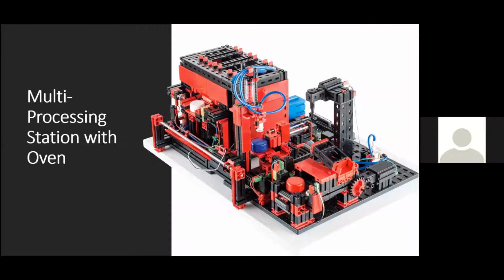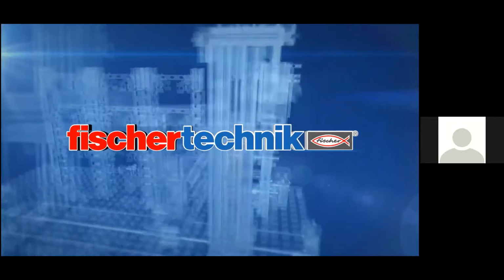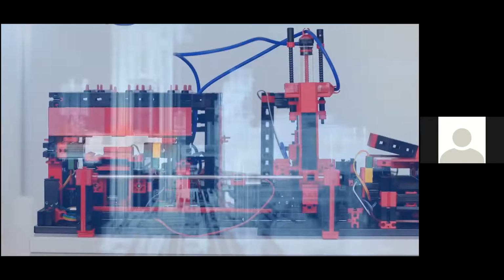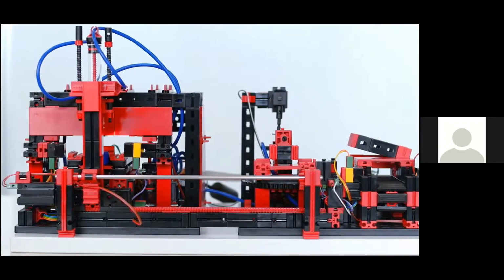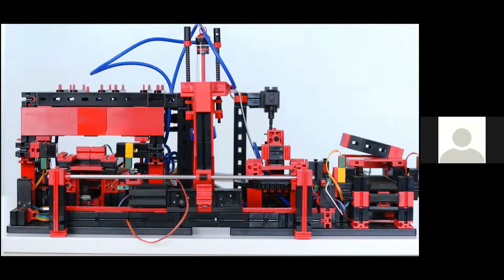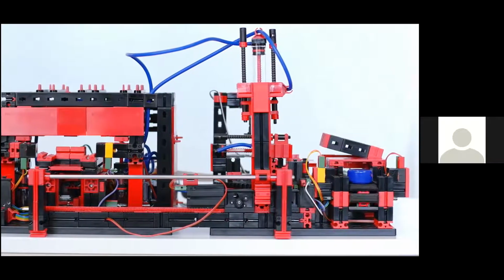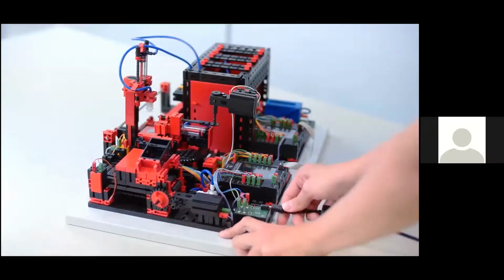The next model we're looking at is the multi-processing station with the oven. This model features a furnace simulation with a pneumatic sliding door. There's a downstream processing station with a pneumatic transfer unit, which includes a vacuum gripper, a cutter with a rotary table, and a conveyor belt. Components used on this model include 4 mini motors, 6 push-button limit switches, 2 photo transistors, 2 LED light barriers, 4 solenoid valves, and a compressor.